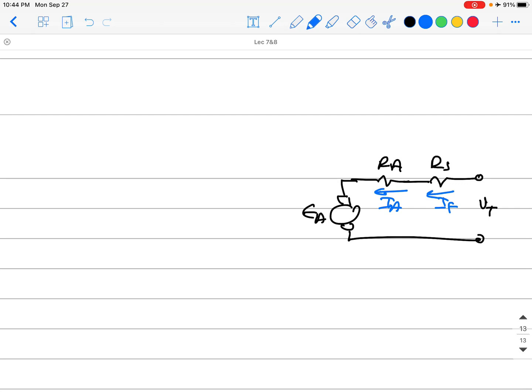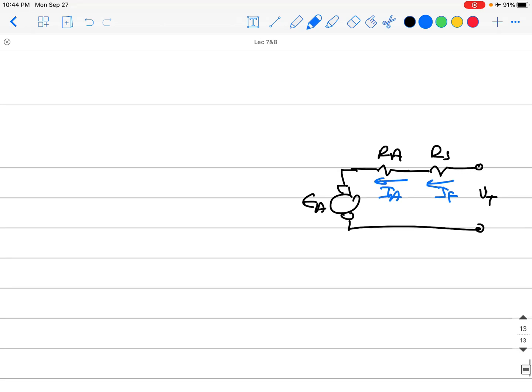It is the contrary here, because I field equals I armature, and I armature is by definition high because it represents the amount of energy converted. So you already have a high amount of current moving through the series winding. As IF equals IA, which is high enough,